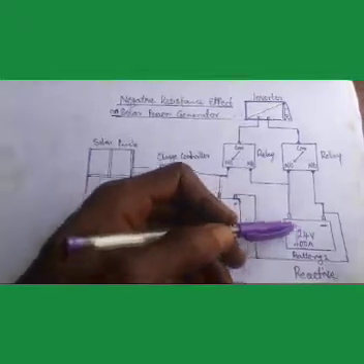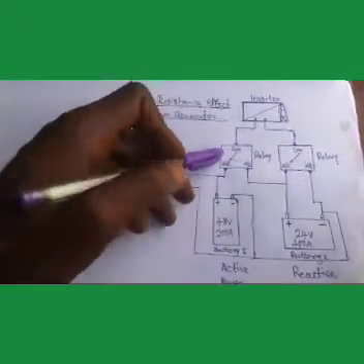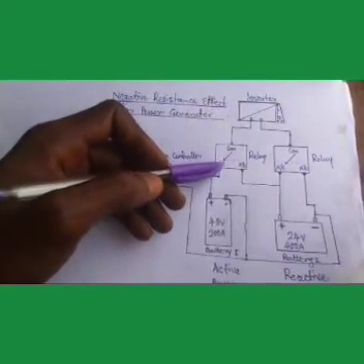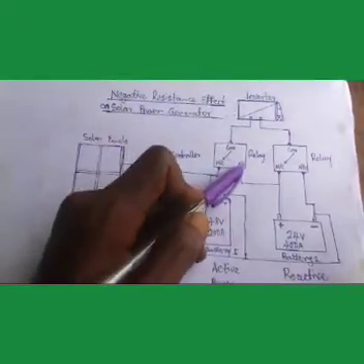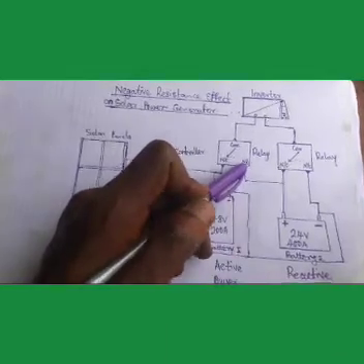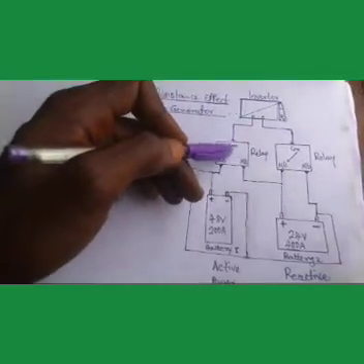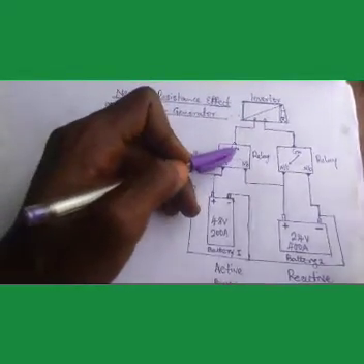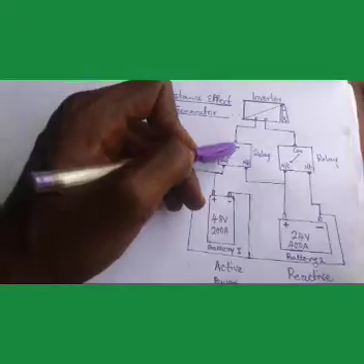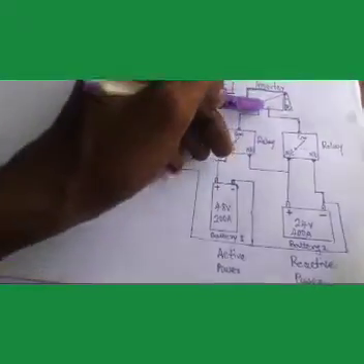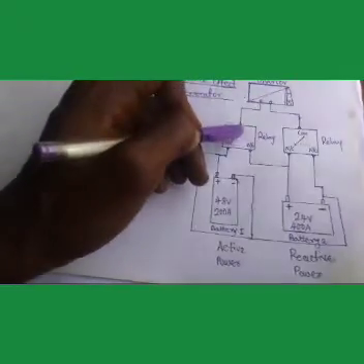you press a button switching this relay from normally closed to normally open. Now at that point, this relay is triggered. It is energized. This common is now connected to the normally open, which is your positive terminal of the relay.